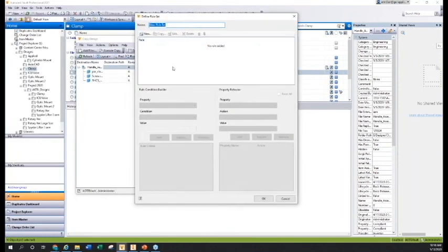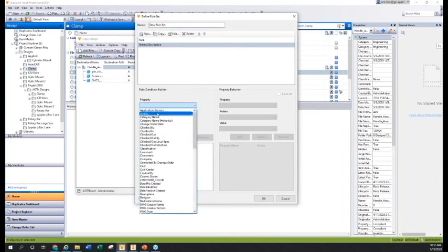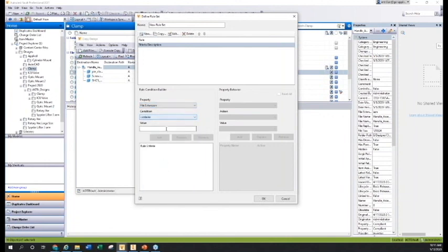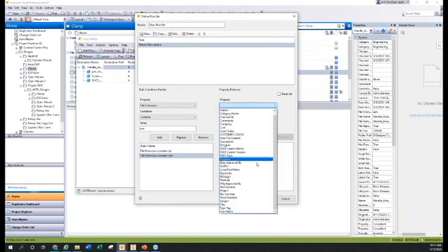Just putting it on my other screen. And down at the bottom here is where I wanted to show that. Let's say we're creating, maybe this is title to description. So basically during the copy design process, I want to map that rule. So we'll say anything with, I don't know, we could do file extension, I guess is a pretty common one, contains IPT, add that, and then maybe IAM, add that. So if it contains any of those while we're copying, we want the property, what I say, title.